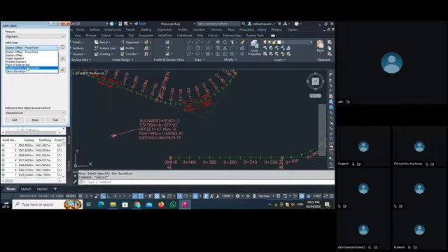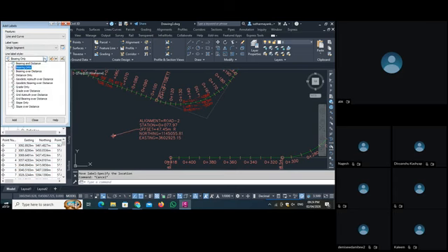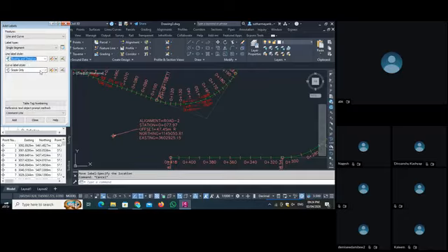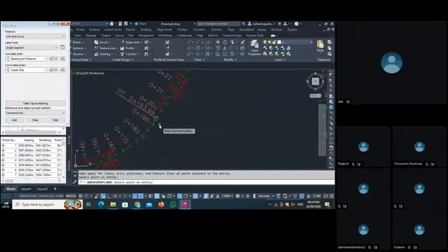Then we have the multiple segment, single segment, point of intersection, station offset, and all those things we saw here. See, when we go for the line and curve, if you want to know the line and curve, you can select the bearing and distance. For the curve, if you want to show the grade, then add this here, click on the alignment. So all those things you can show here. It will be messy, I will provide everything here, but don't worry.